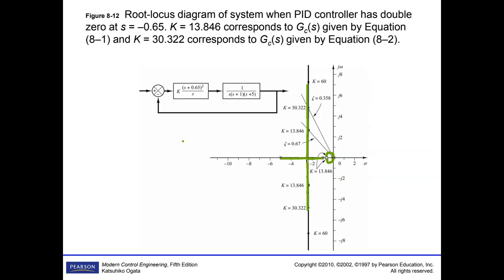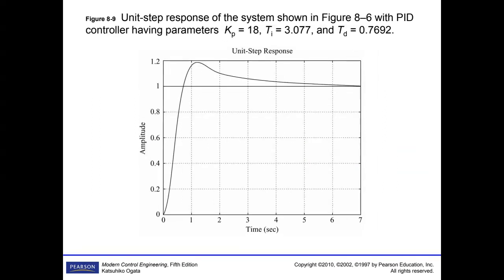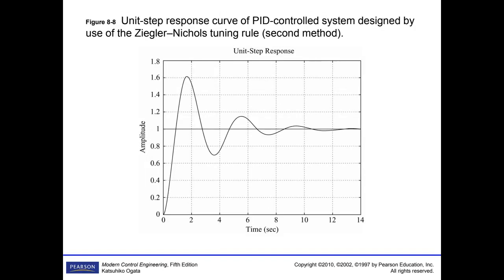Now I'm going to come back. That's the one with 0.6 without. So you can see that the first Ziegler-Nichols method is giving us this one, 60% overshoot and almost 12 second settling time. But if you look at that one, it's nice.